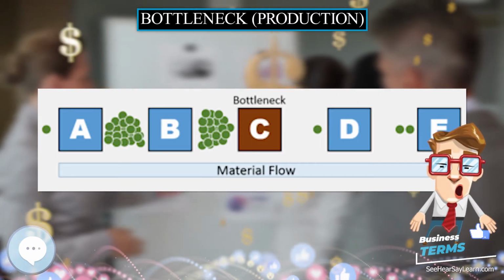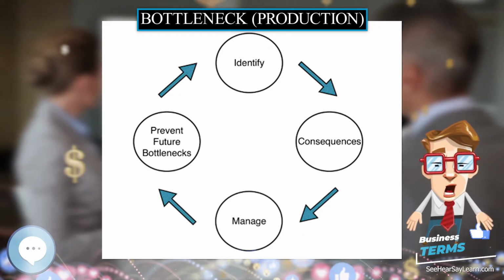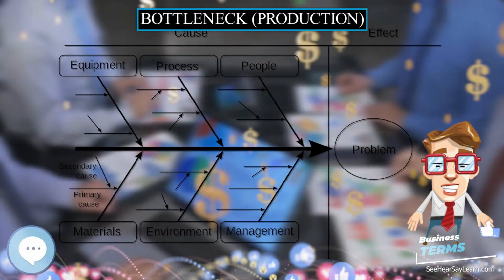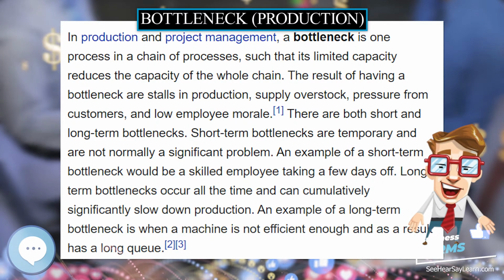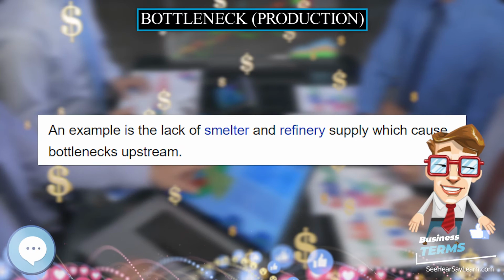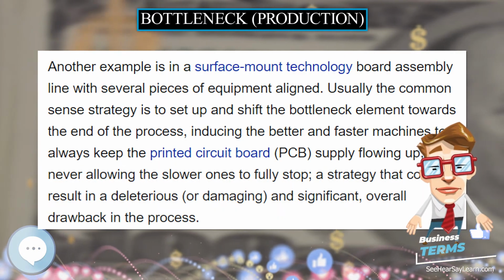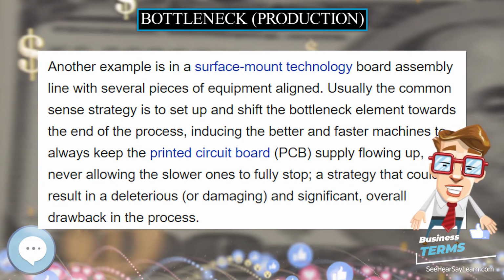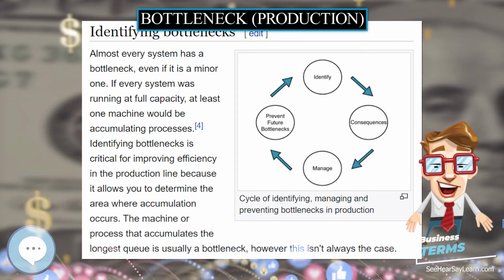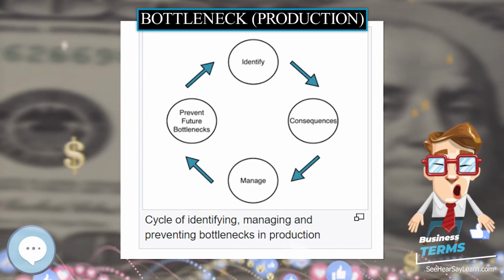Taking into account the layout of the different processes can also increase efficiency as it minimizes delay caused in the transportation stage. The use of a proper layout can reduce the overhead of machines and can reduce material handling time. Establishment of standardized exchange protocols can minimize the potential for future bottlenecks to occur through minimizing downtime. This increases efficiency by reducing any potential confusion between different sectors and hence reduces the possibility for delays of the arrival of raw materials. Static and dynamic systems and shifting bottlenecks.